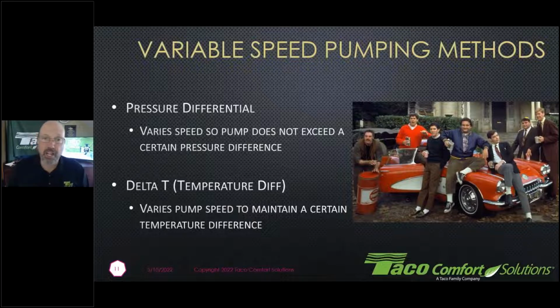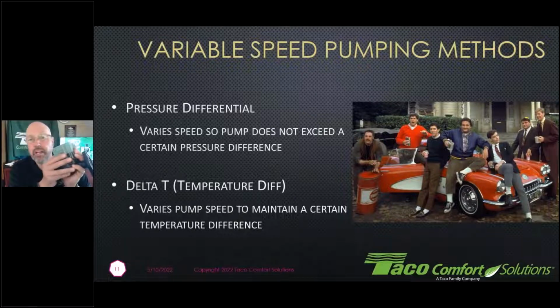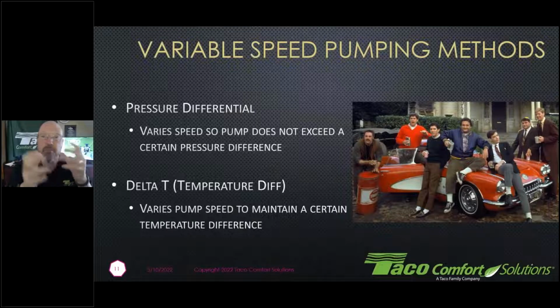Now, a pressure differential style circulator does not read pressure whatsoever. There are no pressure sensors, no pressure transducers, there's nothing out there that's going to read pressure in the system. What an ECM delta P circulator looks at is an amp draw and an RPM. It's an algorithm, a calculation that is done to maintain the speed that we need the circulator to run at based upon the zones that are opening and closing, or if you had thermostatic radiator valves or proportional valves that are changing the flow characteristics of your system. So like I said, you're not going to find them both in the same circulator.